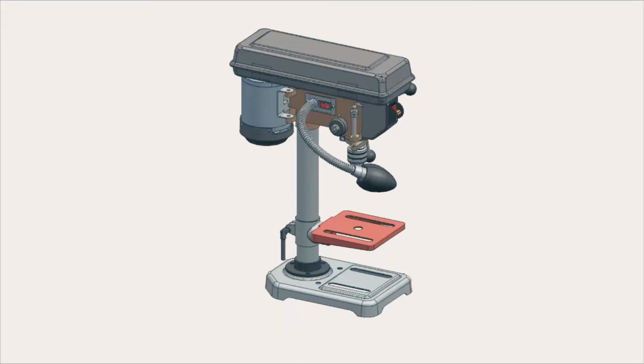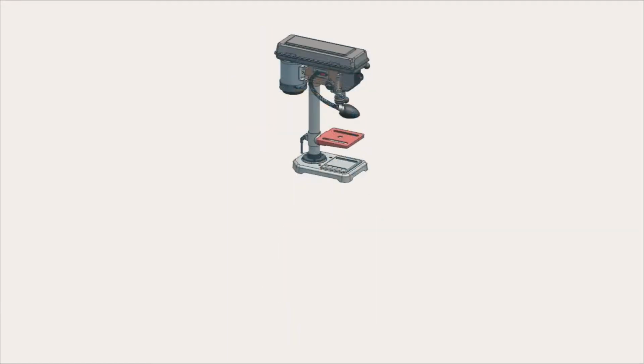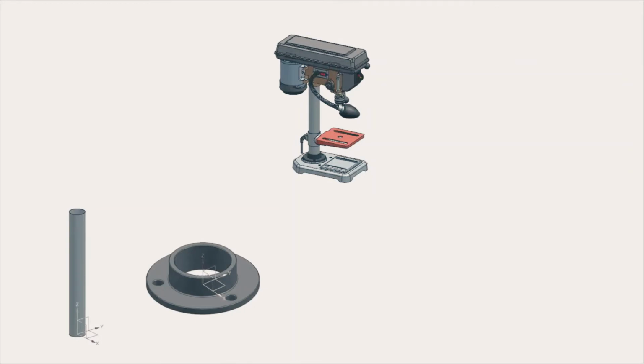If you are new to NX, this series of Day 1 training courses is designed to get you started. You'll model some of the parts in this drill press assembly, beginning with the column. It's simple to model, with one sketch that you extrude a distance. The column support is a Revolve sketch, with some detailed features added.